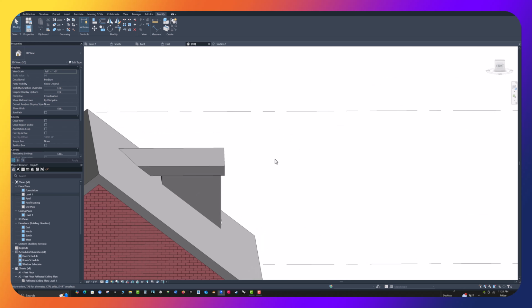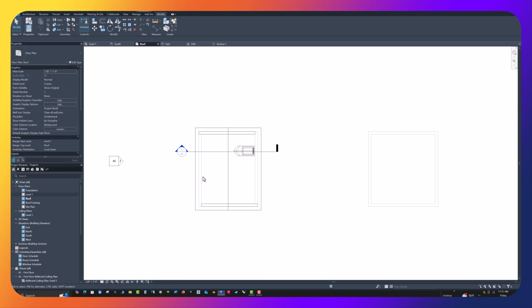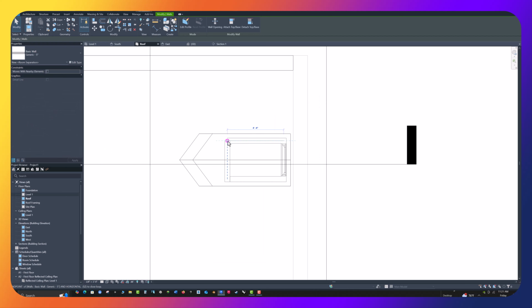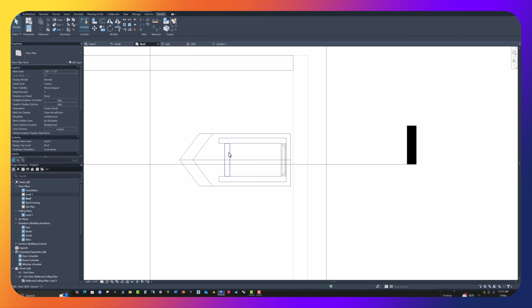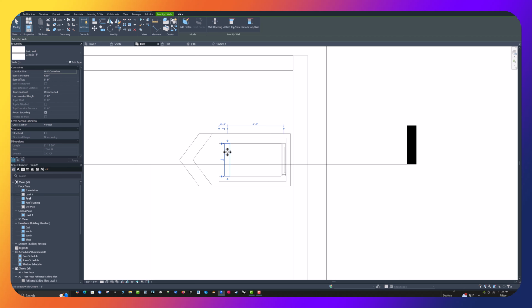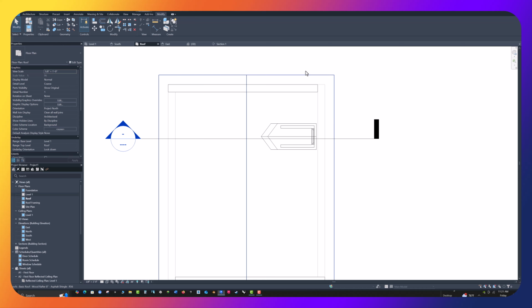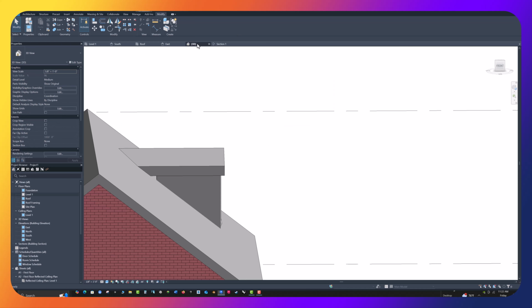And you notice these walls need to go back a little bit, so I'm going to go back to my roof plan and grab these walls here and pull them. I don't need this wall, so I'll get rid of that wall. Okay, there we go. We're looking pretty good here, I think. I thought I had done that.